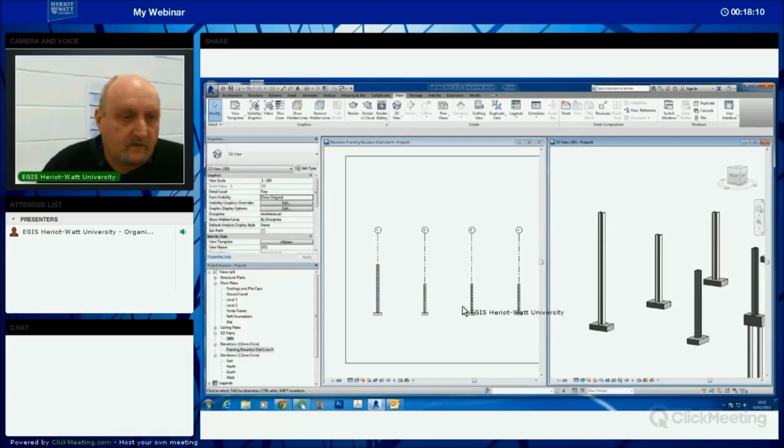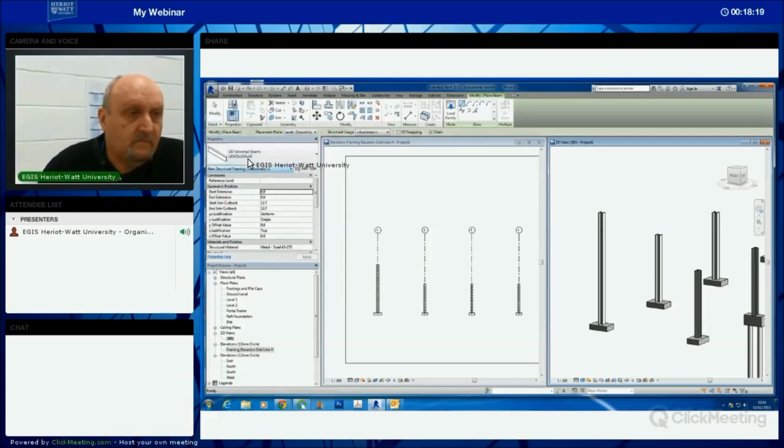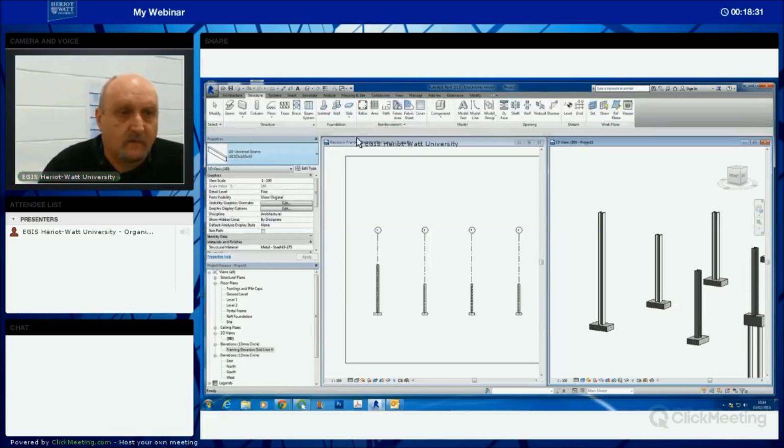And hopefully in the 3D view, you can actually see it appear, not quite by magic, but it will appear. So I'm going to model the portal frame in here, and I go to Structure, Beam. Now this is 305 by 165, quite a lightweight beam. It's not terribly lightweight, 305mm isn't that small, but I'm going to load in a larger one so I can show you how to do that.